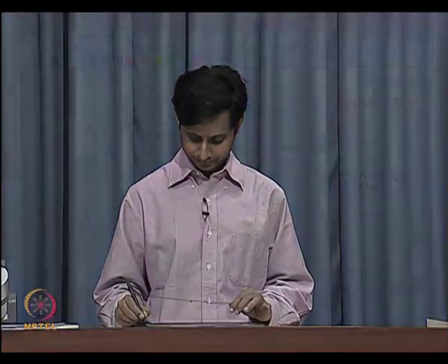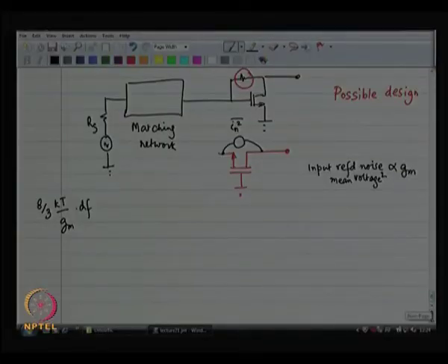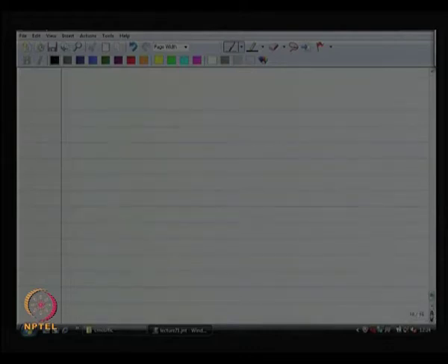Channel current noise is increasing, but it is as if I applied a lower noise voltage at the gate. So, it is not desirable to have something which is proportional to GM. That means that at high frequencies, when I need large GM, I will get a lot of noise from the MOSFET itself. Okay. So far so good.